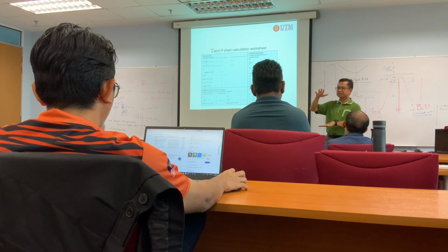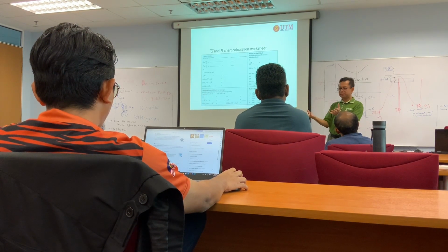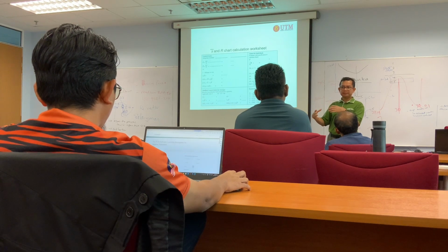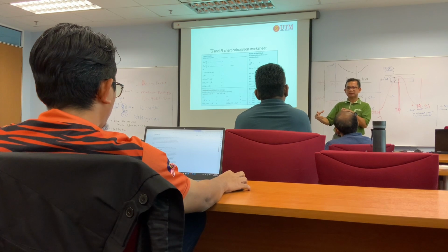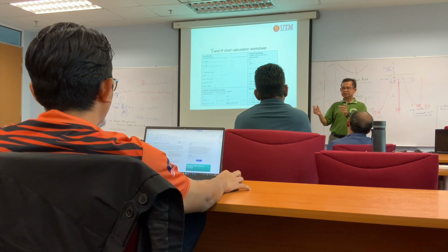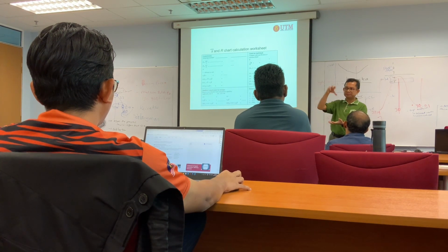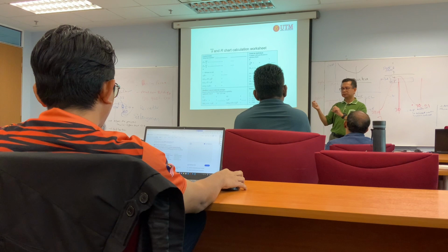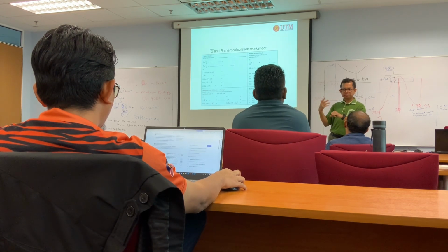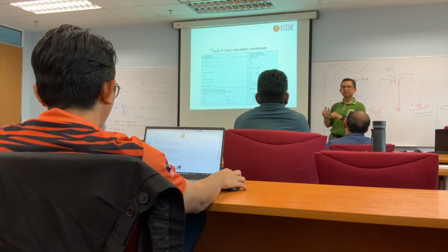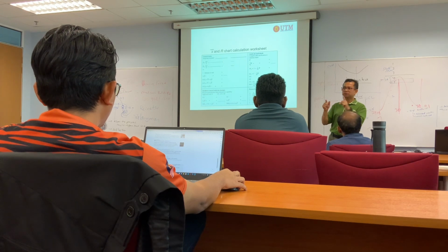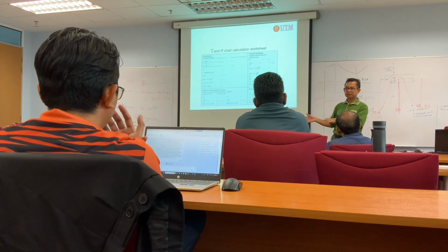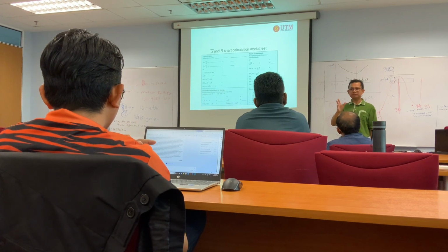So they also have problem on the stamping. When we want to stamp the sheet metal on the die, there is a calculation, stamping force and so on. And then the clearance of the die depends on the material as well. So when you change the thickness, the dimension of the die should be different, because the clearance should be different, and then the stamping force also different. So they have problem, ageing problem. So they need to rework that process. So they need workers to do the after-process rework. So there's a cost.